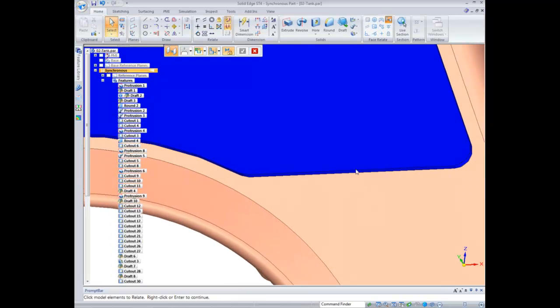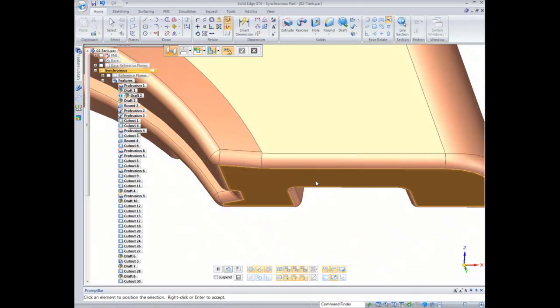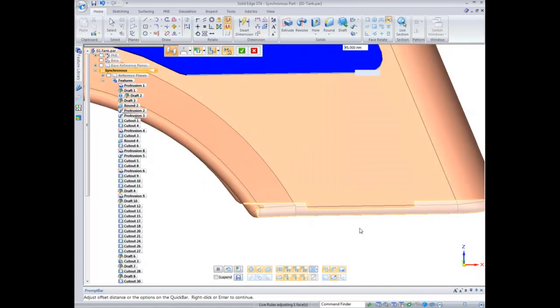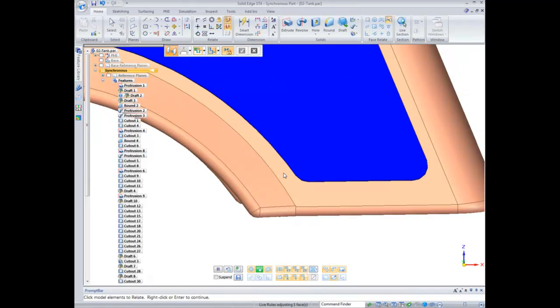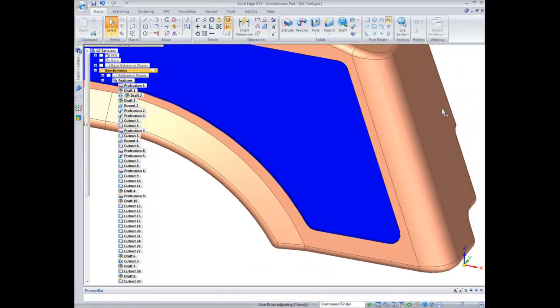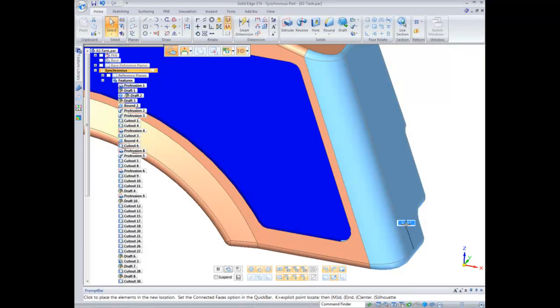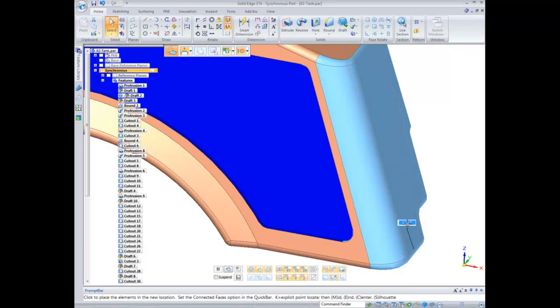And if we do one more over here to the bottom face, enter in a value, it keeps this radius constant offset since we applied the offset up here, and it's persisted. Also, we can come in here then, and if we want to change the angle of this face, it'll keep that offset constant since we had it persisted.